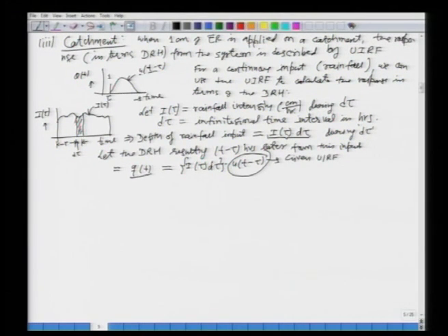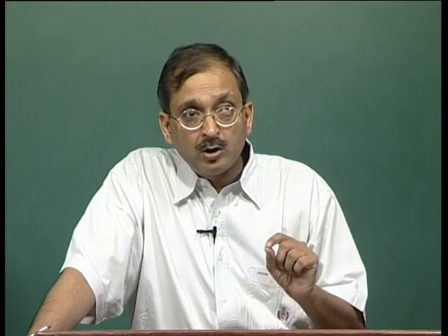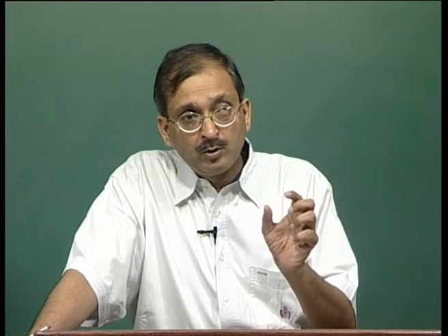And what is this q t? This q t is the response from this system due to this infinitesimal strip of your rainfall, which is expressed by this. Okay. All right. So, now I have written the expression or calculated the response from this very small input I tau d tau, which occurs in d tau.